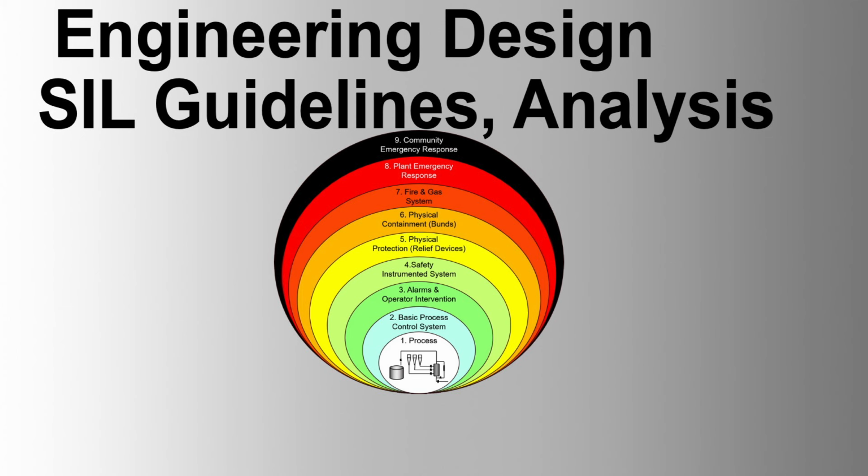7. Verify SIL requirements. Ensure the PFDAVG of the SIS meets the SIL requirements of the Safety Integrity Requirements specification. 8. Modify configuration if needed. If necessary, modify the configuration, hardware configuration, functional test interval, hardware selection, etc., and repeat the process from step 3.